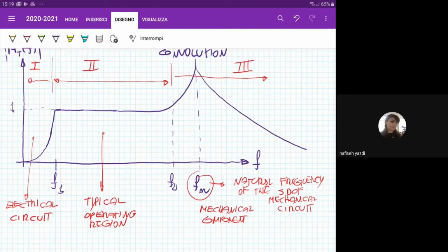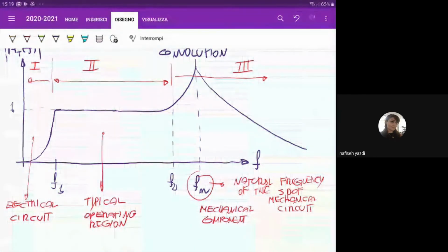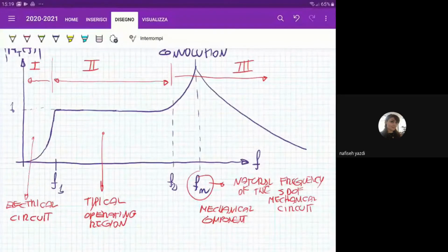So, all said, the second region is the perfect one, okay? That is characterized by practically a constant line. That is, the transfer function between the output and the input is not dependent on the frequency content, and that's what I like. It is very, very nice. It's just a matter of having the factor that is translating the output voltage into the acceleration, unknown. Okay.